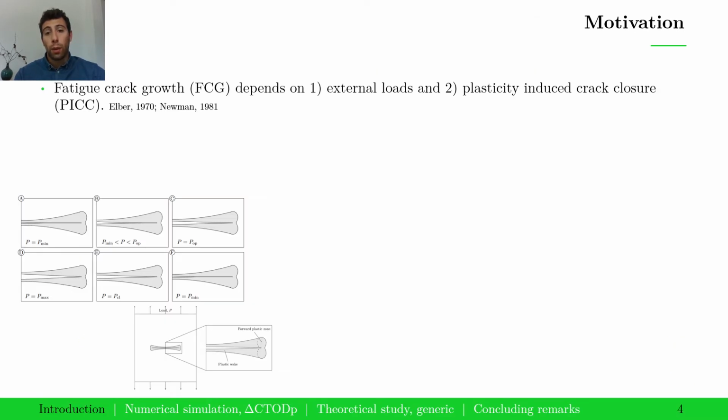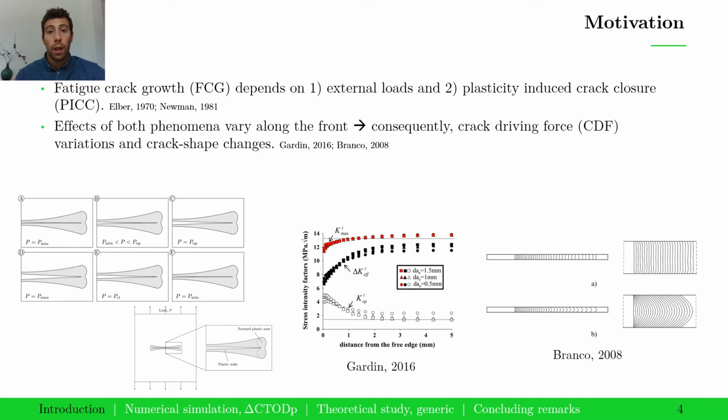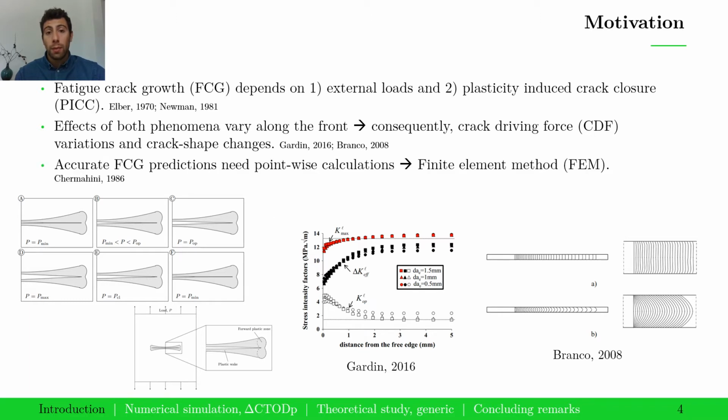Fatigue crack growth not only depends on the external oscillating loads, but also on plasticity-induced crack closure, which is the wedging effect produced by the crack face contact during part of the load cycle. The thing is that in general scenarios, the effects of both phenomena vary along the crack front. So consequently, the crack driving force displays through-the-thickness variations and the crack shape changes. This means that fatigue crack growth should be predicted by pointwise calculations, being for that the finite element method the most popular approach.